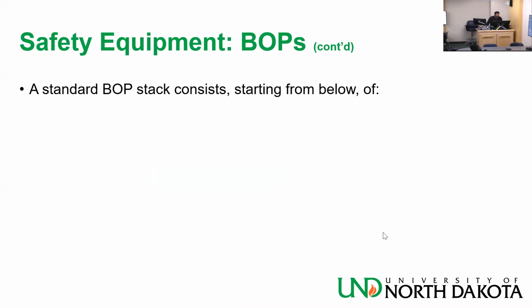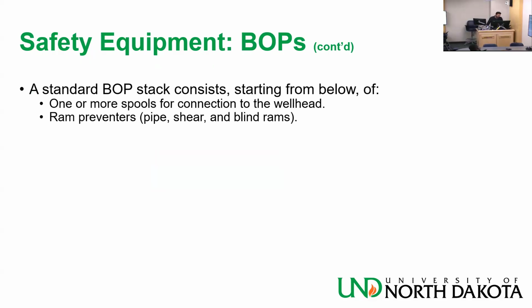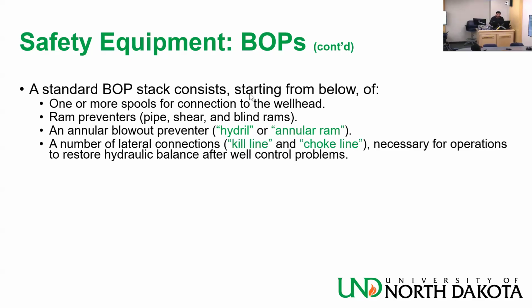Safety equipment. A standard BOP stack consists of, starting from below, one or more spools for connection to the wellhead. That's where you connect the BOP. Ram preventers, that's what we talked about, blind, shear, pipe, blind shear combined as well, a lot of stuff. An annular blowout preventer, also known as hydril or annular ram, that's the balloon.